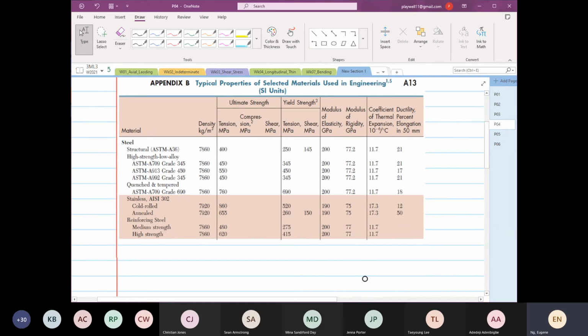So what we are designing is for ductile material. For ductile material, we don't look at ultimate strength. We look at yield strength for ductile material. So what you observe is for tension, there are a lot of values. You can see all this, wow, tension there. In compression, you only have what? You only have two values. Yes or no?